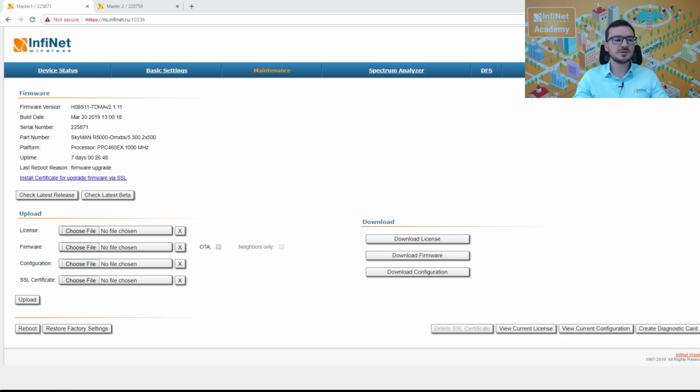Next question, what happens if you choose instant DFS and the spectrum is full? Maybe try the QMXB that has a beamforming antenna, and it can use a narrower beam to connect to the CPEs in case of a point-to-multipoint connection. In case of point-to-point, maybe use some higher gain antennas. This could help in some situations because the beam will be more focused, and this way you could avoid interference coming from other directions.